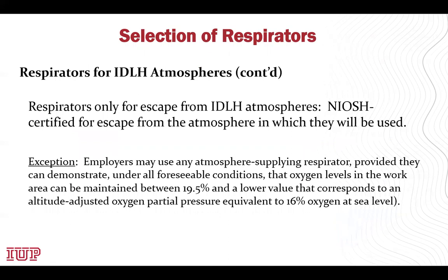Respirators only for escape from IDLH atmospheres need to be NIOSH certified for escape from the atmosphere in which they will be used. There's an exception. Employers may use any atmosphere supplying respirator provided they can demonstrate that under all foreseeable conditions the oxygen levels in the work area stay between 19.5% and a lower value that corresponds with an altitude adjusted oxygen partial pressure equivalent of 16% oxygen at sea level.